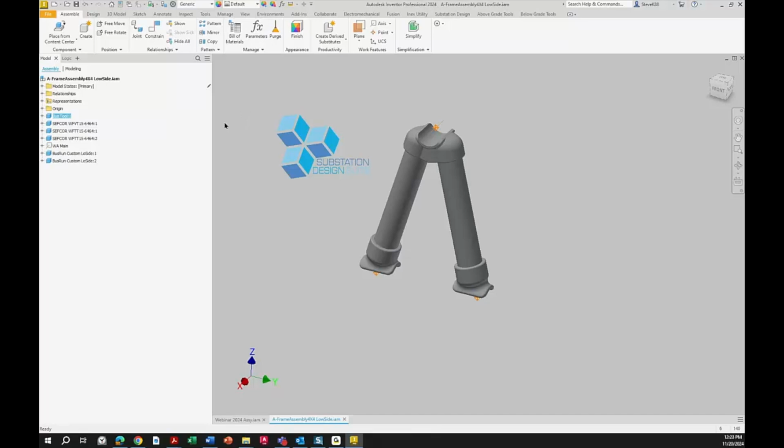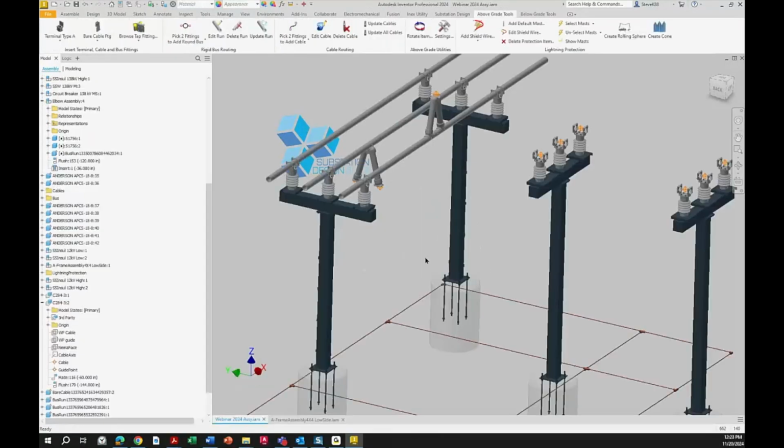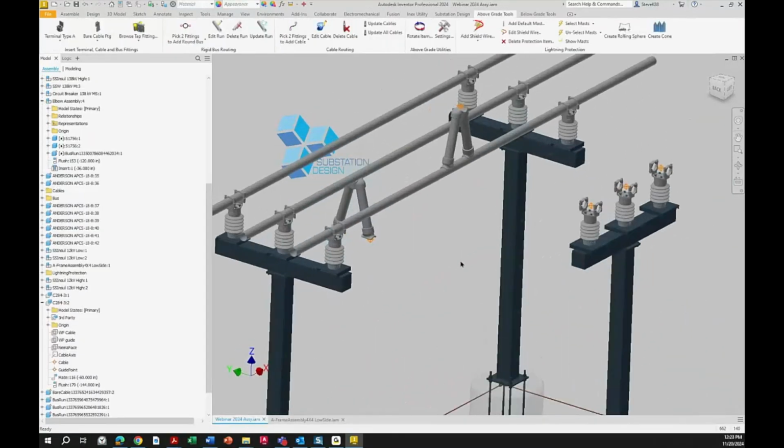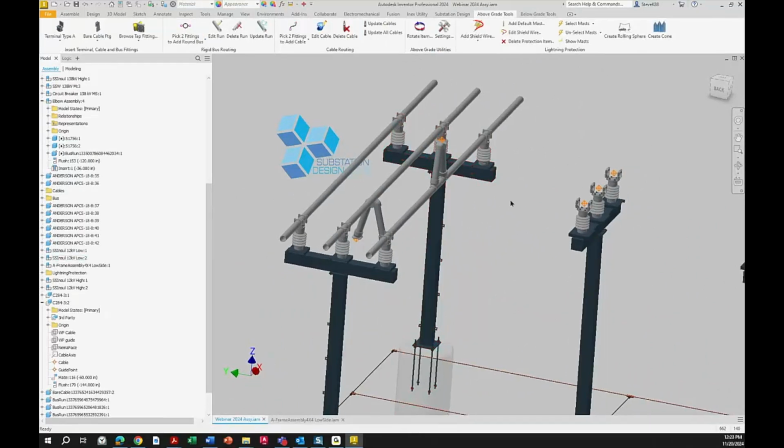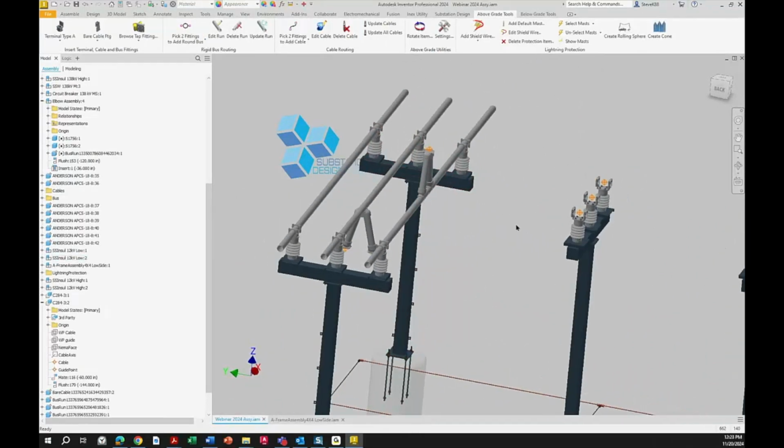If we look closer too, otherwise the first item is the fitting here. So typically you would make this with the first item, probably that top fitting, and it will place it for you. But do you always want to place it that way? Sometimes you need to place it because you don't have the pipe ready yet. We'll go back to here, and you can see here that I don't have a piece of pipe overhanging here because I don't have a destination yet for that pipe.